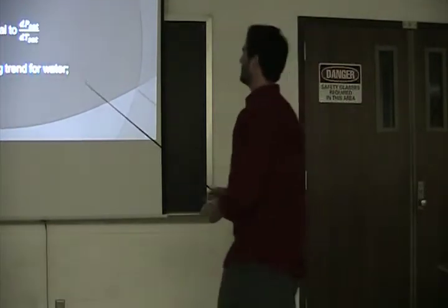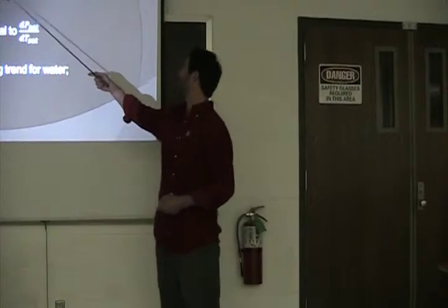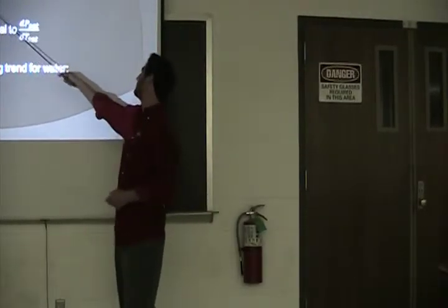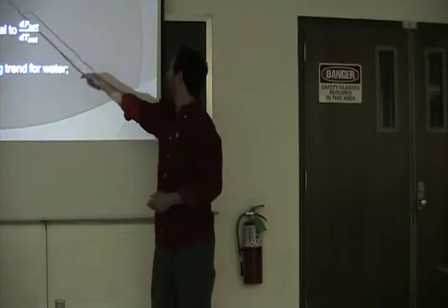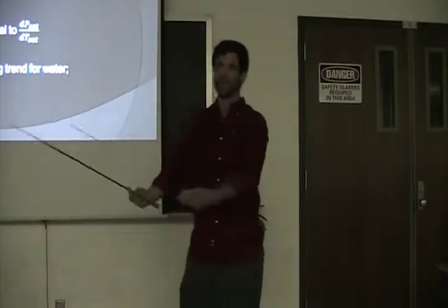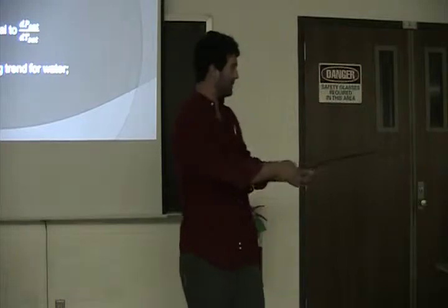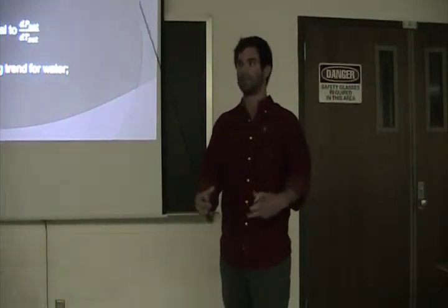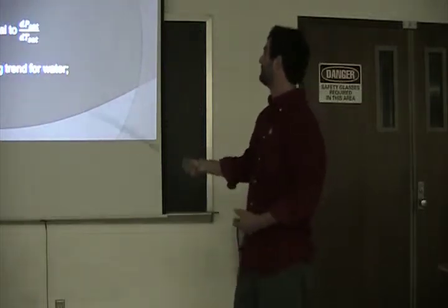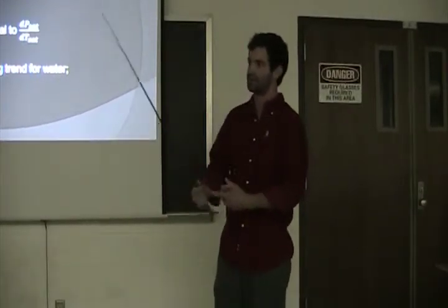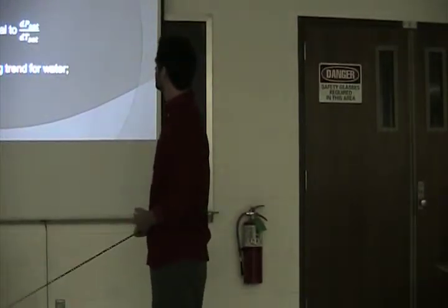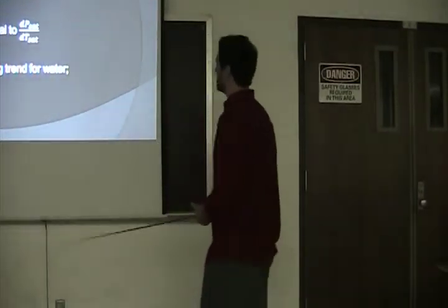For all of you that don't remember, the enthalpy of gas, h_g, minus the enthalpy of liquid, h_f, equals h_fg. So the gas has a certain enthalpy, the vapor inside the test tube, and the liquid has a certain enthalpy. The difference between the two is what we want to find: the amount of energy that you have to add to change states. And it's proportional to the slope of the curve that we were talking about.